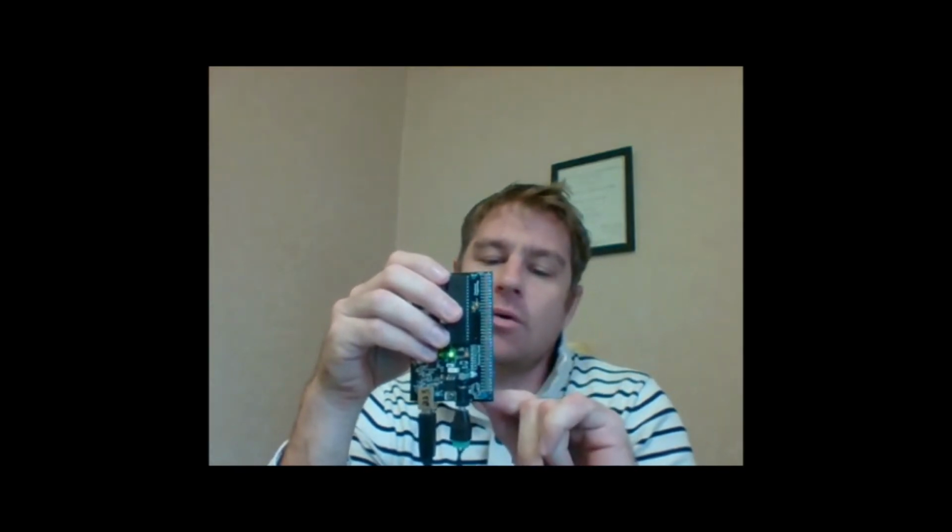Okay, so how will I connect this? Well, normally on a breadboard you have two rails on each side. Okay, and one of them is going to be a ground and the other one is going to be a supply, right? So you've got to make sure that the ground and the supply are properly labeled. So what I do over here is I make sure that my ground is in the blue.